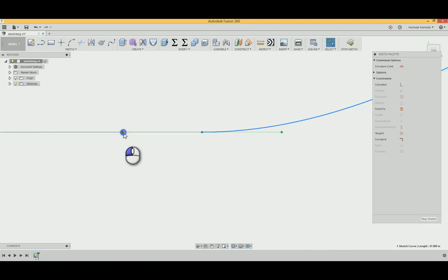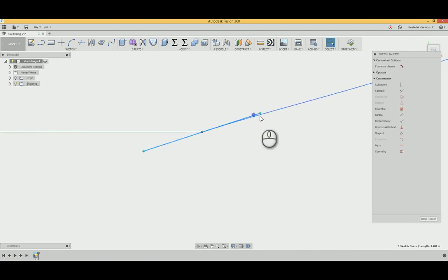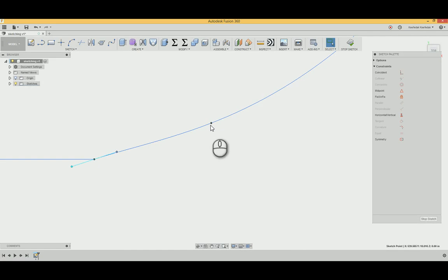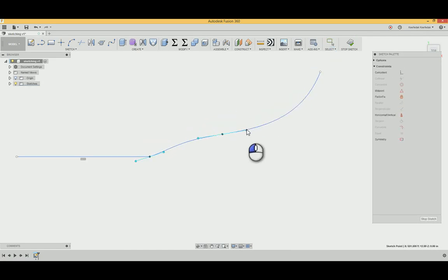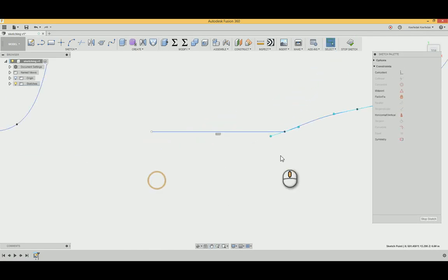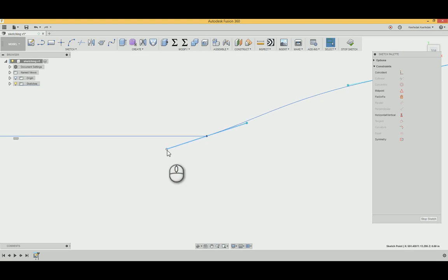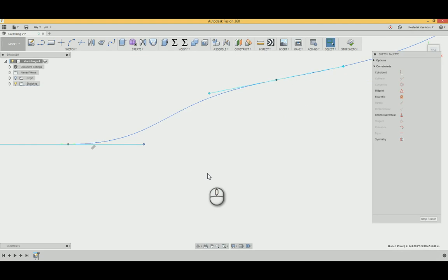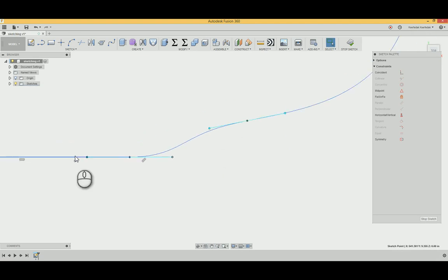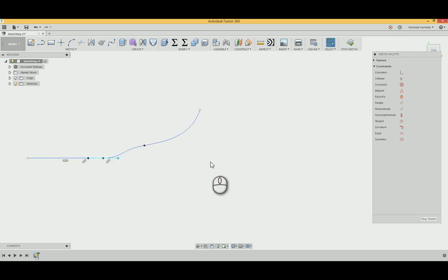This bar here, you're going to notice on these splines that you can change the curves. And what you can do is grab that bar, that handlebar, and you can actually snap it to the line like that, and now it flows into it. That's my preferred way to do it. Okay, so you have this flow going into it. All right, just thought I'd show you that. They must have changed it. They always update this thing, and I never used to be able to do that.